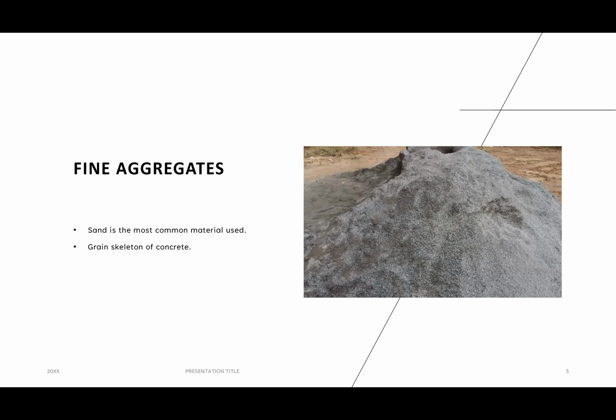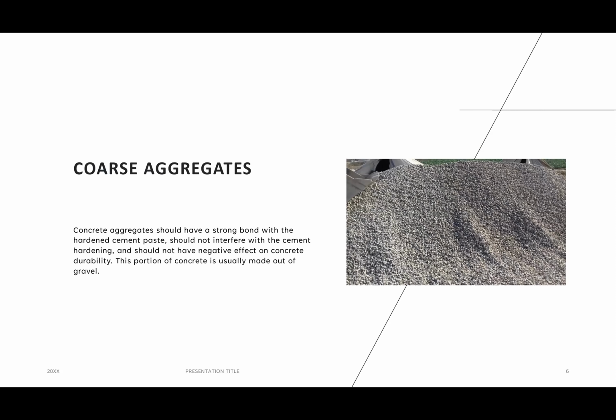You're able to have a substantial influence on the output by modifying the makeup of the fine aggregate, as well as its geometry, size, and other characteristics. Fine aggregates help the mixture to sustain its dimensions. It also has the potential to affect both the elastic properties and the damage tolerance of the concrete. And finally, the characteristics of the fine aggregates have a considerable bearing on the degree to which a concrete will shrink. And pictured on the right is just what that would look like.